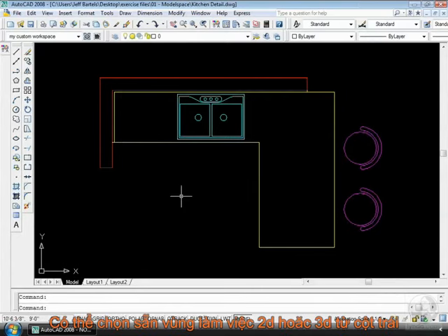Imagine all the different types of drafting that we can do with AutoCAD. We can do two-dimensional drafting, which will require certain toolbars and palettes. We can do three-dimensional drafting, which will require different toolbars and palettes. You may have a day that you spend entirely doing dimensions. Dimensions will require another set of toolbars. Imagine if you had a workspace set up for each type of work that you do. That way, when the time comes, rather than having to redo your interface, you just have to load a pre-saved workspace. When AutoCAD is installed, it already contains some predefined workspaces.